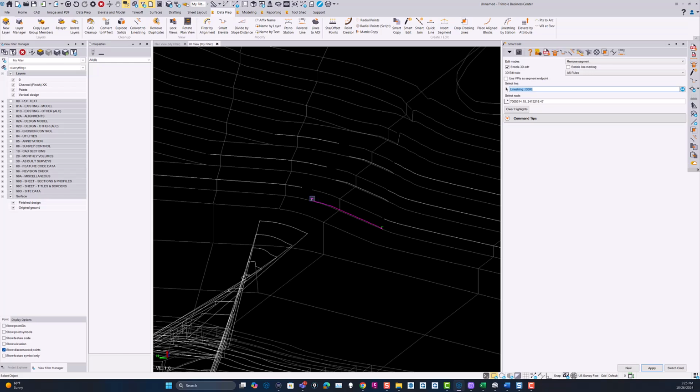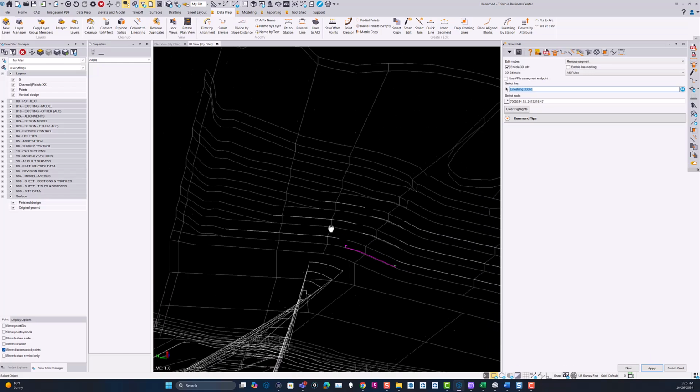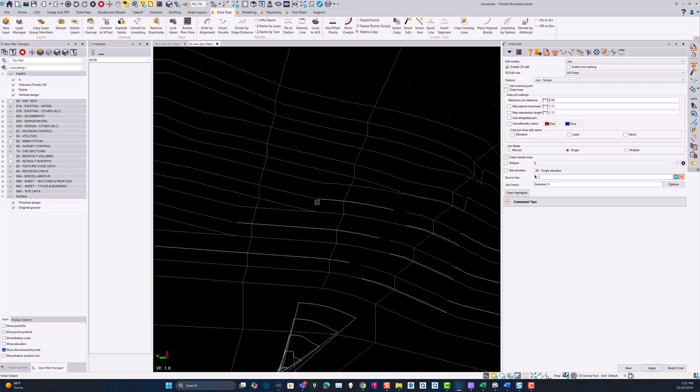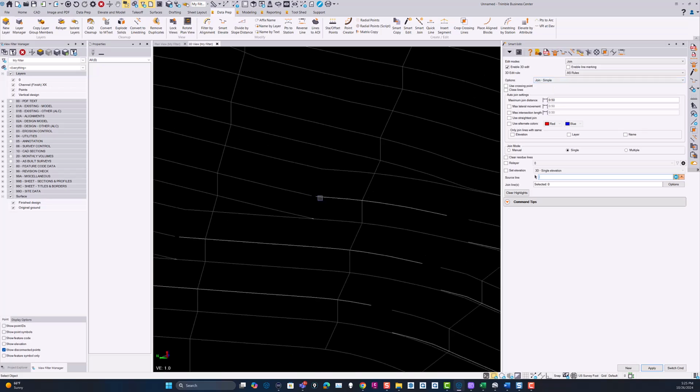And then once you've done that, you can then jump from the edit mode into the join mode. So you hit the J for join, and now you can go into the join functionality and say you want to join simple mode, which will just put a line segment between these. You could say join by mean and move the endpoints to the mean location and join at the mean location, but I'm going to use the simple mode. And then all you're going to do here is you're going to go between line 1 and line 2.